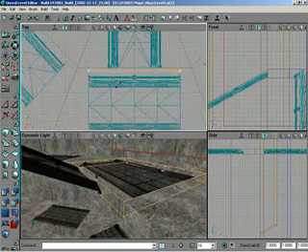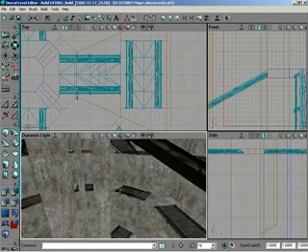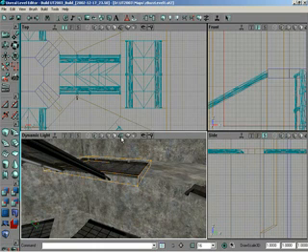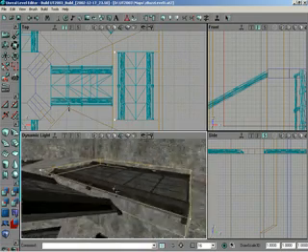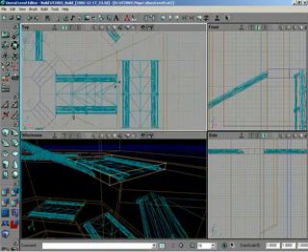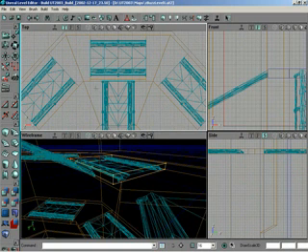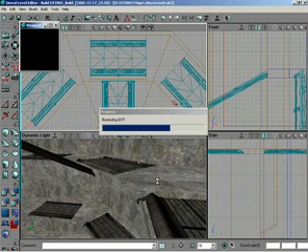So fast. So, 2 brushes left. Grab this one, move the camera over, wireframe perspective, that brush, normal, zoom in a little, Control-Alt, drag, 1 in, and move on to the final brush. So let me grab these, 4 more vertices, 1 snap. I'll go back to my camera mode, deselect, and let me do build all. So we can see what this looks like now. Very cool.